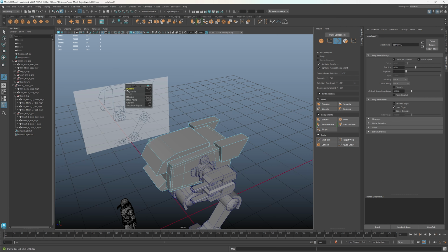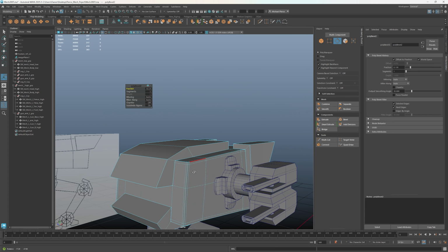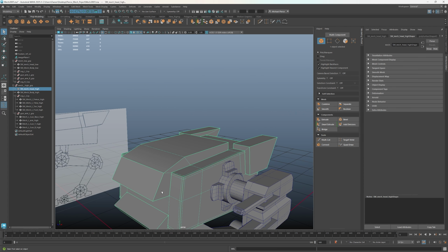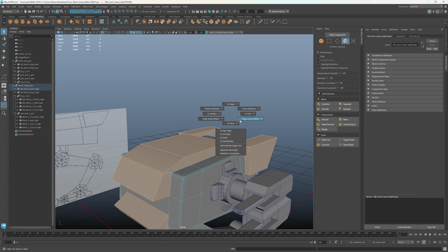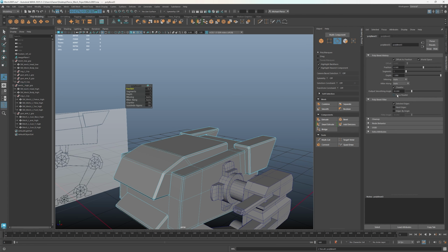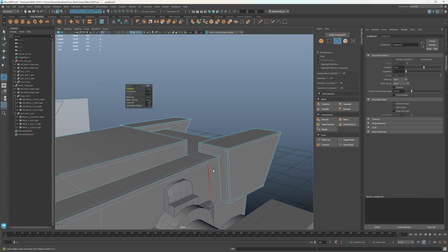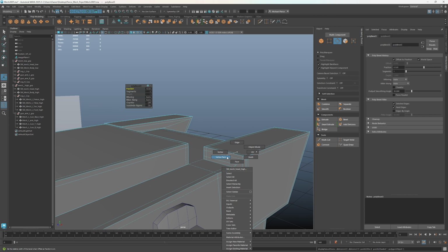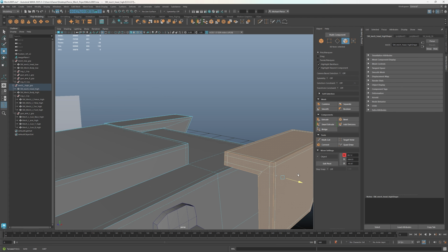And then do it that way. And then I'll do the same for the other ones. So just shift double clicking these guys, holding control, right clicking, and then going to, oops, not two faces, two edges to edges. Do the bevel, make sure I turn it on hard edge only, and also turn off the chamfer. This will give us nice even topology, except for still getting that weird effect when I bevel this. Oh, but it's still at least separate now.